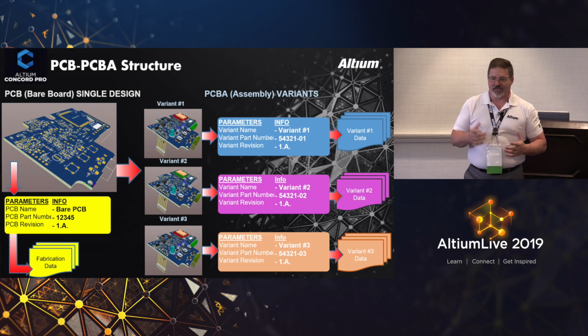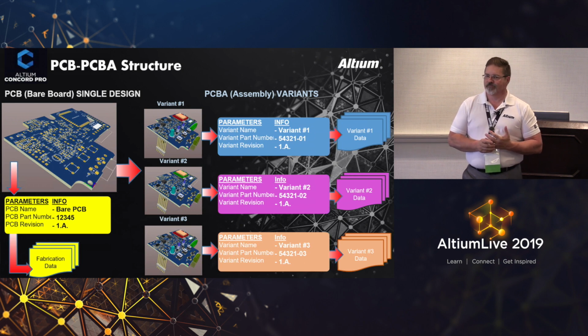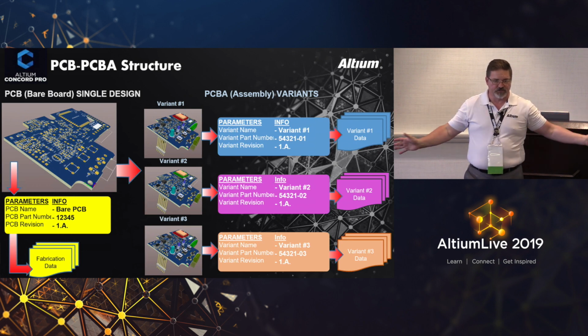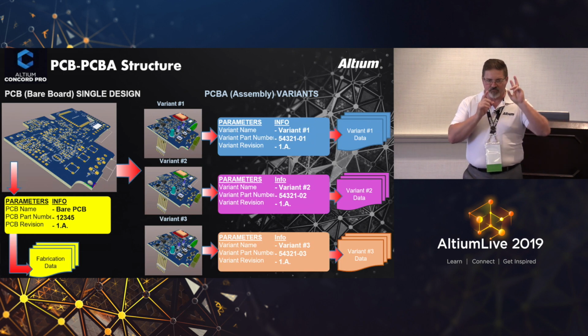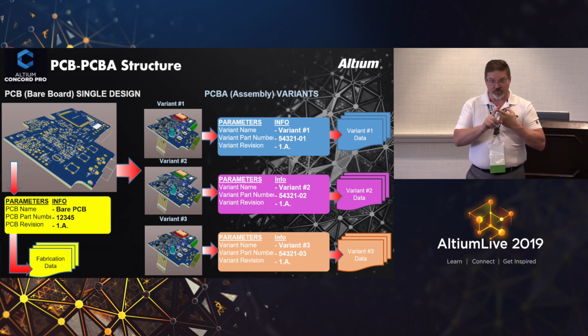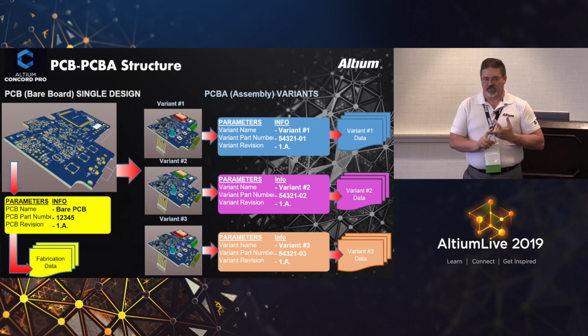I have an industrial version of my product. Relays are missing, and there are various features that other products don't need. Exactly. This becomes very helpful for companies because they can build one PCB and have multiple units they build from that one single PCB. Just by, and the choices are this, not installing something or having an alternate component.